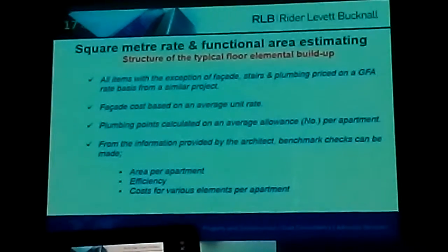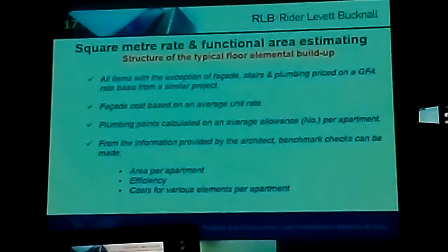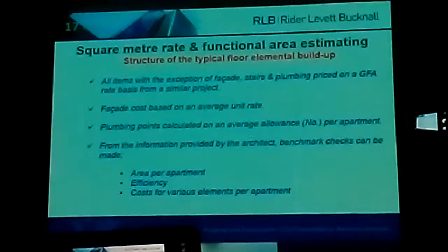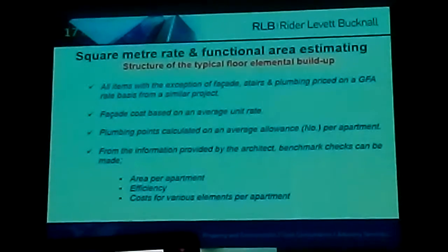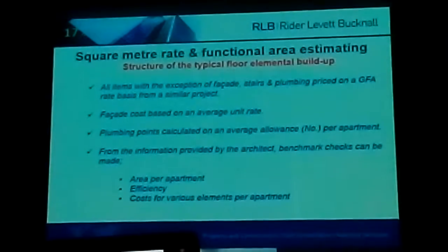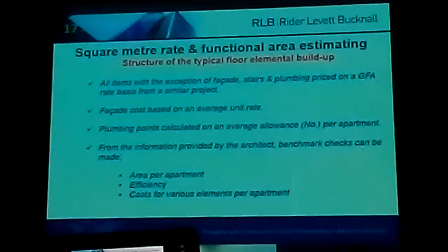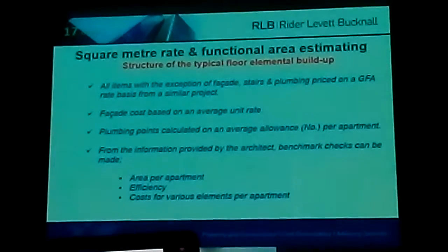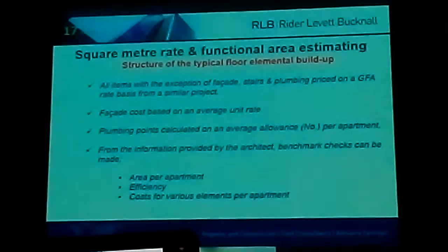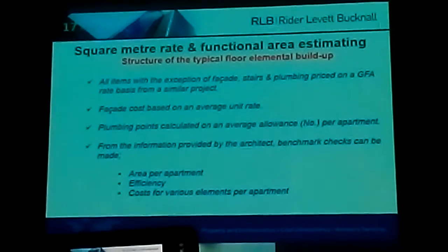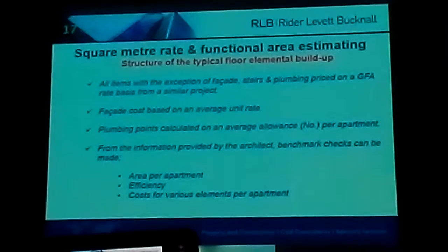Here are the key fundamentals of that typical floor build-up. All items with the exception of facade, stairs and plumbing were priced on a GFA rate basis, typically from a similar project. Facade cost was based on an average unit rate, which is a basic measure of girth by the height.